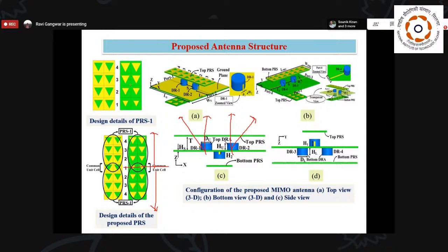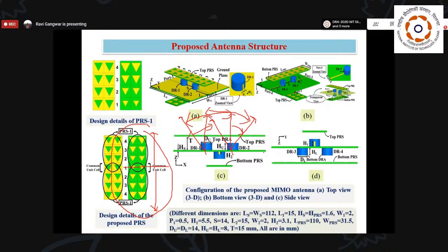If you are going to the same stream, then this beam is going to be excited in this direction. In that condition, there is no field separation. We are not able to get any isolation improvement. What are we going to do? We have to design this structure in such a manner that each antenna deflects the beam into its particular axis, not with respect to your DR1, so that the correlation between their fields is going to be better and our isolation is going to be improved.